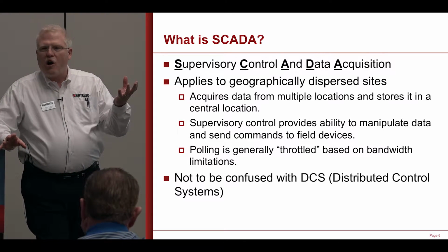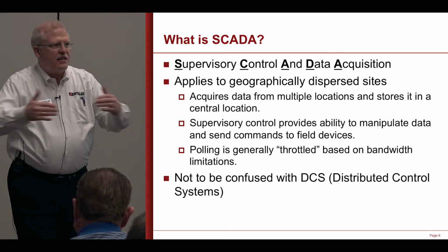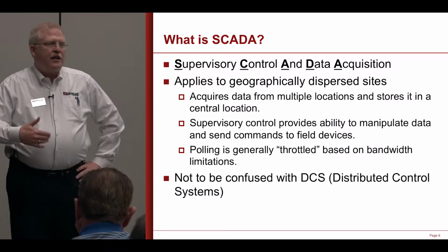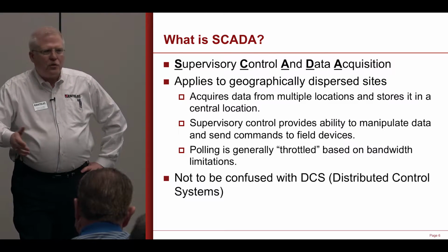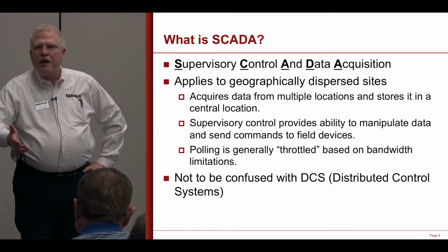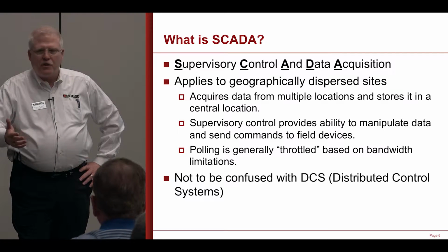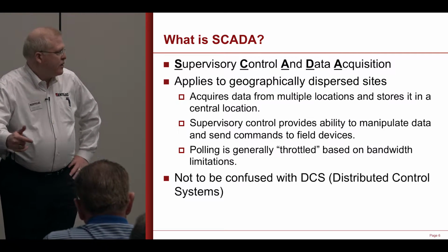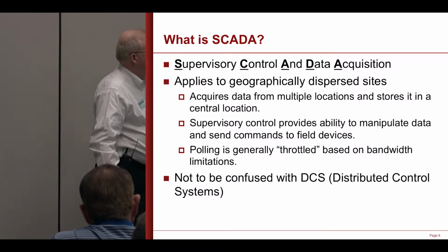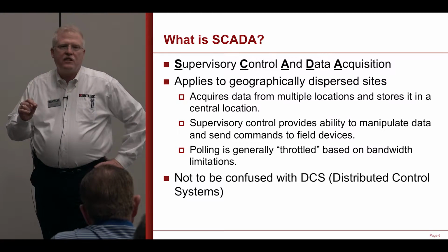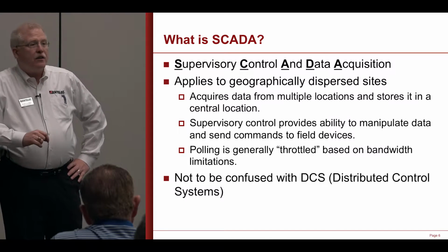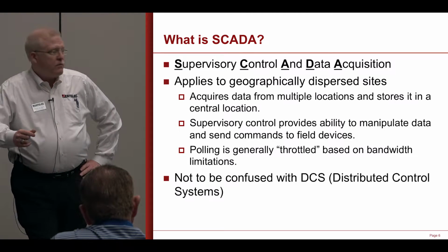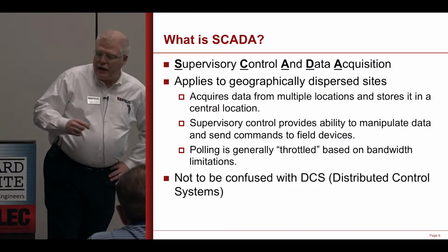So they're almost always used on a system inside a fence. And they're almost always on some kind of Ethernet physical communications backbone. They may bolt in some wireless and some other things to get some points, but the critical portion of that control in a DCS is very different. So SCADA systems and DCS systems are fundamentally different when you get to how they communicate underneath. So I'm going to spend my time talking about SCADA.